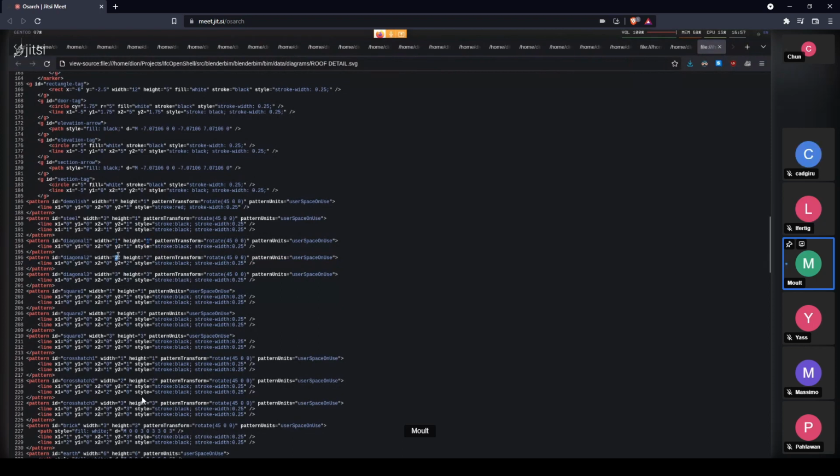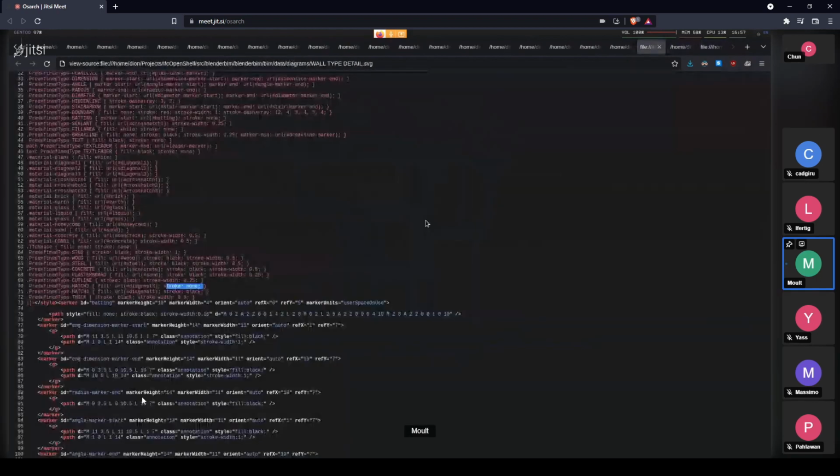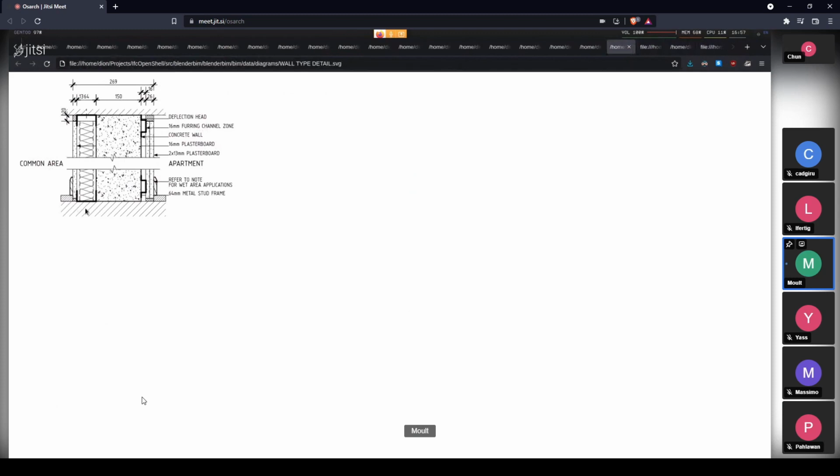This is a 2 millimeter apart diagonal line. This is a 3 millimeter apart diagonal line, and so on. So hatch 3, which would use diagonal 3, means that this one here is exactly 3 millimeters apart on paper. If I took out a ruler and measured it, that's what it would be.